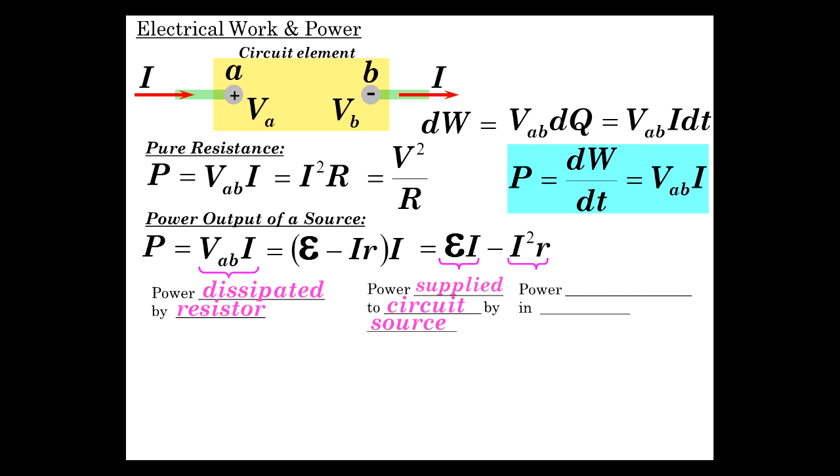Speaking of itself, there's that internal resistance. And this resistance times I squared is a power term. That is the power dissipated by its internal resistance. So that's power dissipated in the source. This is what causes the battery to heat up. If you ever feel your laptop on your lap, with the battery pretty close to your leg, you might feel it getting really warm. Part of that is because of this I squared R.